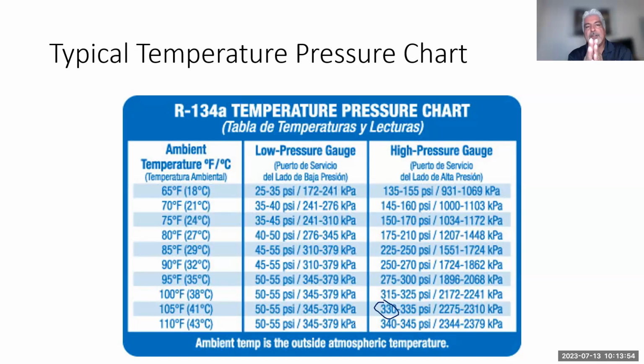So what happens? If there's less amperage than there should be going to that compressor clutch, that clutch is going to start slipping intermittently with that friction as the belt is driving that compressor along with that clutch. And if it's slipping, what is the temperature now? Because that friction is generating some hellacious heat. It gets so hot that it'll actually seize the front bearing of that compressor and the clutch assembly, not to mention fry the clutch. So friction is a big enemy there. I call it the pancake effect. Bang, it engages, and it should stay engaged. But if it's slipping, then we definitely have a problem. So again, voltage drop testing across that compressor clutch is very imperative as you're testing it.